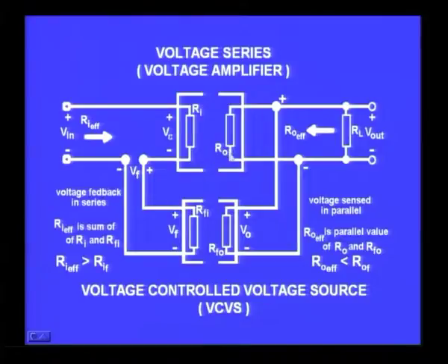This is a voltage source which is taking care of the gain factor of the amplifier, which is in this case the open loop gain. I have not shown this because I am trying to look at it in terms of the Thevenin's equivalent circuit, and therefore the voltage source is shorted here, and what you see here is only the output impedance R0.